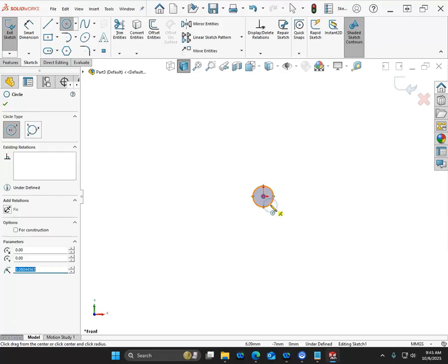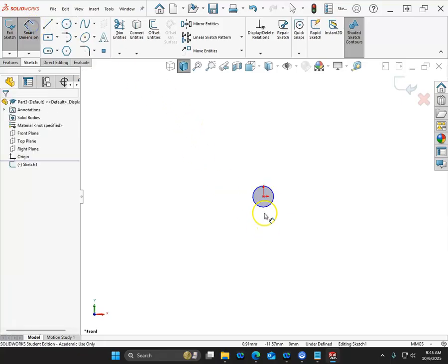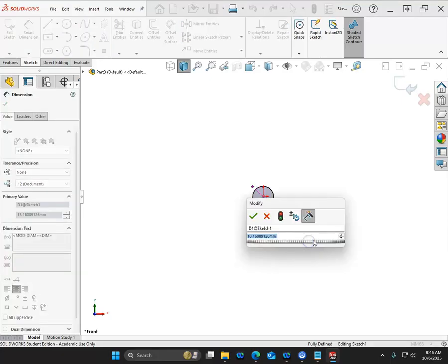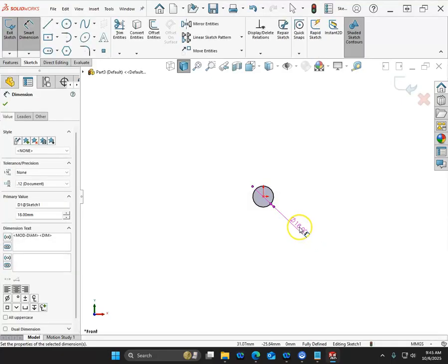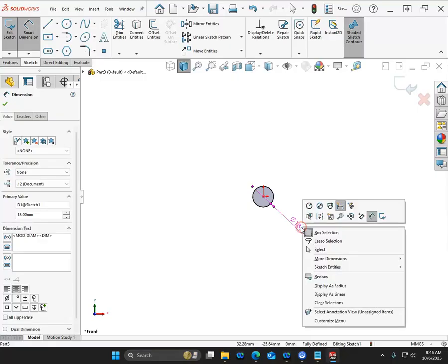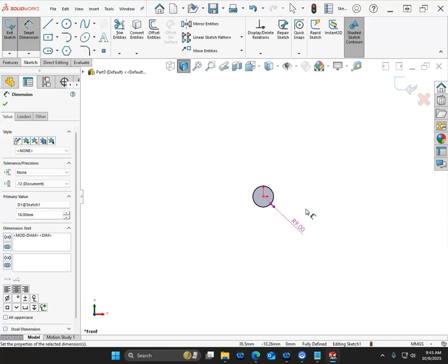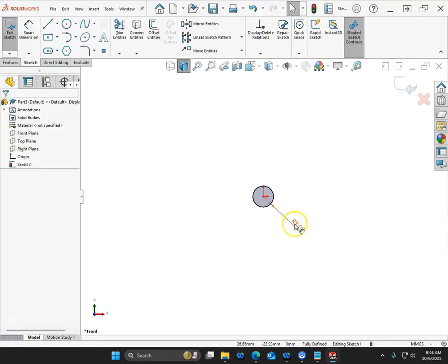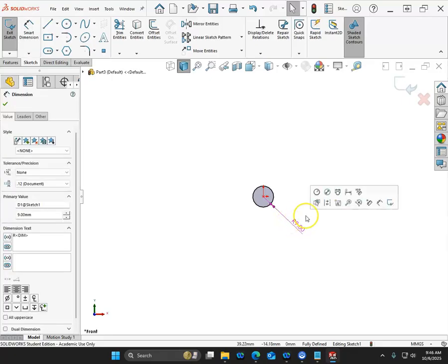Get started with the lower circle, which is given as a radius of 9, so we'll double that, 18. And then because I want to see it as the radius, we're going to right click. So I did try a left click there, but it's still in the dimension command. So we go ahead and hit escape. Then if I'm outside of the dimension, I can go ahead and display as radius, the left click.